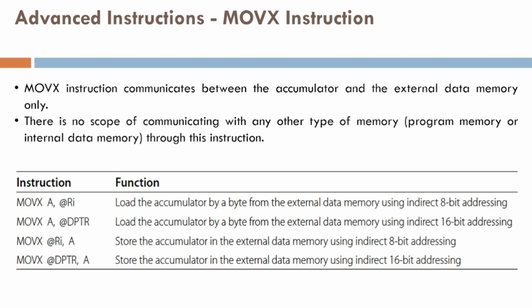External memory is addressed using 16 bits. So the microcontroller needs to generate a 16-bit address in order to fetch any data from the external memory. In order to do that, we will have to use certain techniques, which are highlighted in the next section of this lecture.